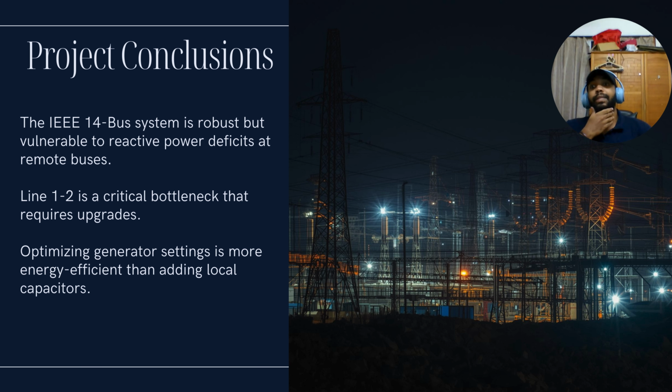Also, we demonstrated that to fix this issue, we can use localized fixes like the shunt capacitors, or we can use a system-wide stability fix by increasing the set points at the generator. But that's still not overlooking the major issue in line 1-2. So my recommendation is to upgrade line 1-2 to handle more load.